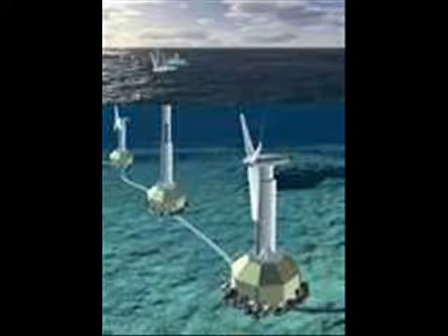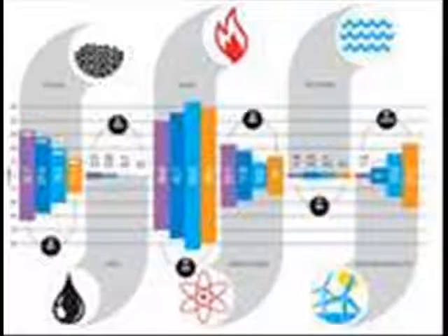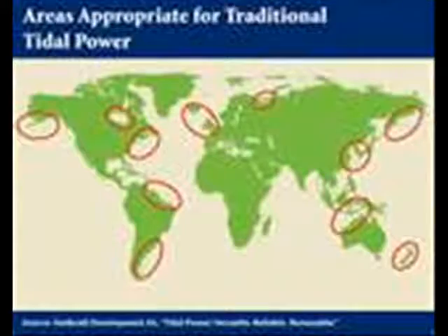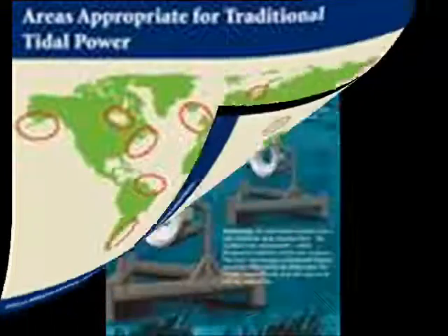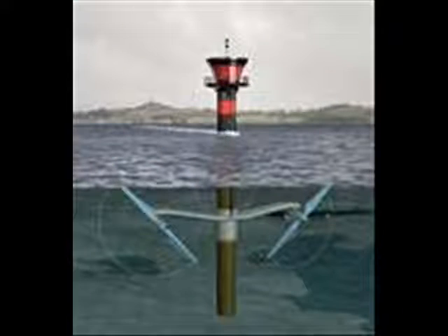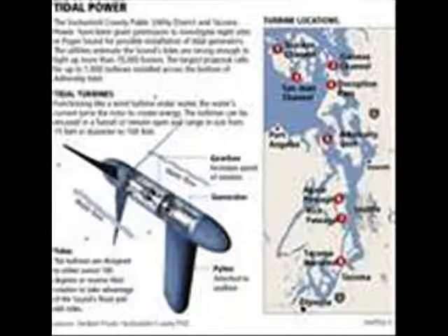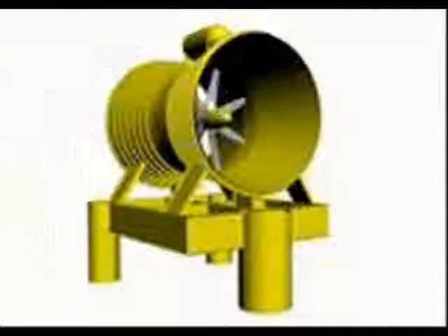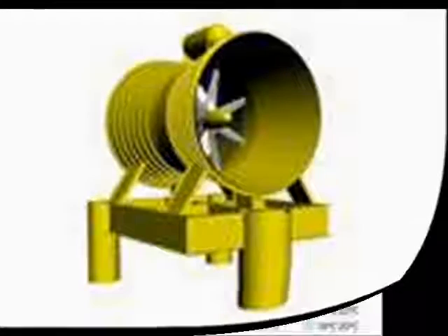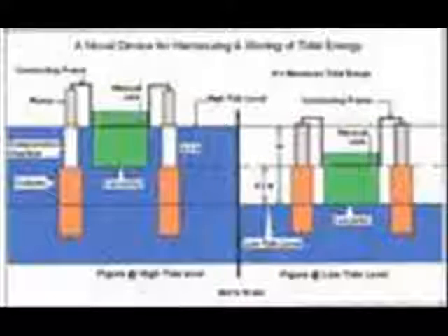Electricity can be generated by water flowing both into and out of a bay. As there are two high and two low tides each day, electrical generation from tidal power plants is characterized by periods of maximum generation every 12 hours with no electricity generation at the 6-hour mark in between. Alternatively, the turbines can be used as pumps to pump extra water into the basin behind the barrage during periods of low electricity demand. This water can then be released when demand on the system is greatest, thus allowing the tidal plant to function with some of the characteristics of a pumped storage hydroelectricity facility.